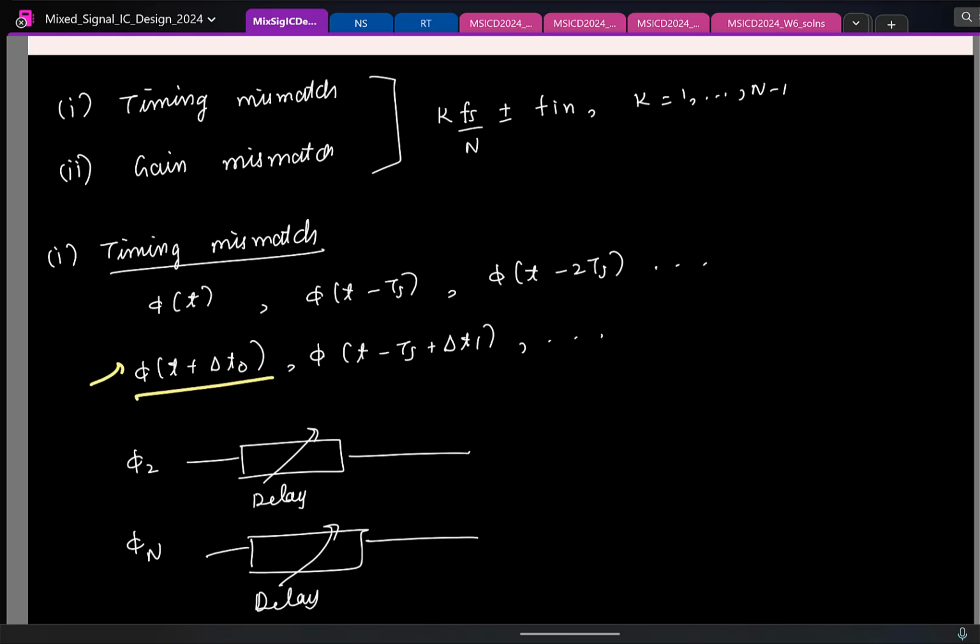So again, variable delay line is pretty simple. This is a digital signal. And how can you delay a digital signal? Remember, delay in your circuit is coming because you are having capacitors. You need some time to charge or discharge the capacitor. It's a digital signal. You can basically buffer it like this. And let's say you put a capacitor.